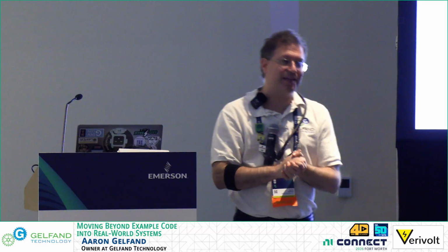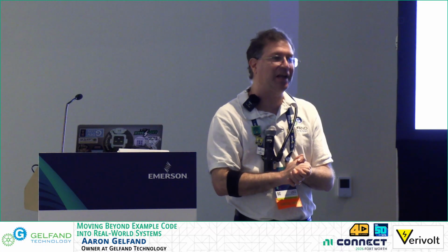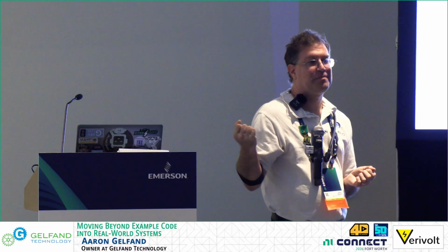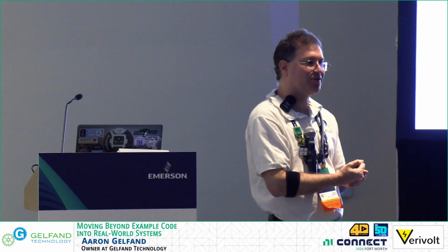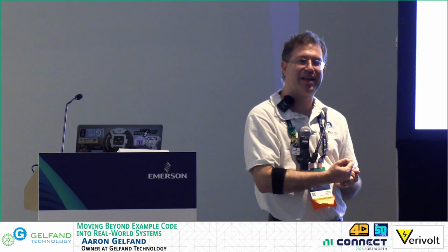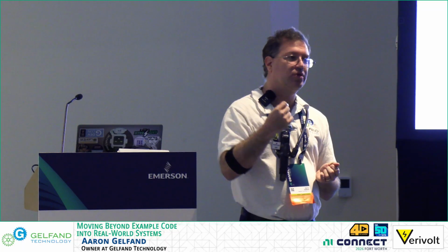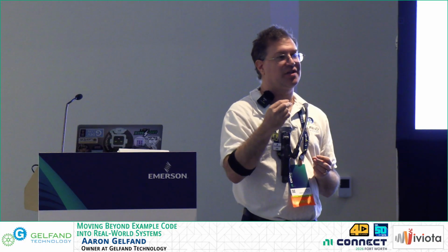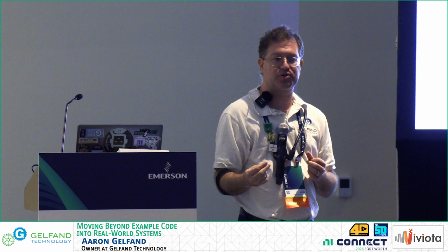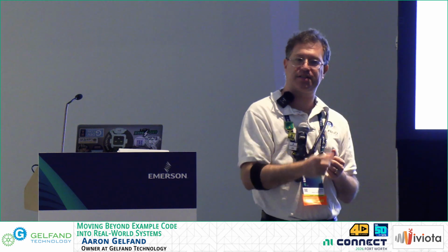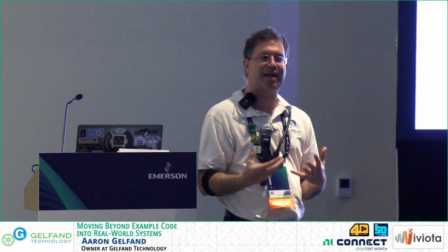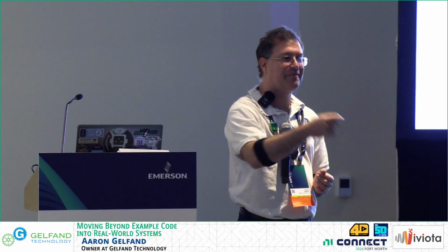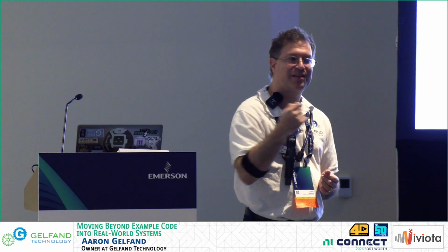The answer today is yes. For the NI USB cables, it is. They will re-enumerate to the same one. But if I plug in a different NI USB 232 adapter, it will get a different COM number. Windows allows tracking by device identifiers and additionally sub-tracking by serial numbers. But if your driver doesn't choose to implement that sort of option, then every time you plug in the same device, it's going to be COM4, COM5, COM6, COM7, COM8.